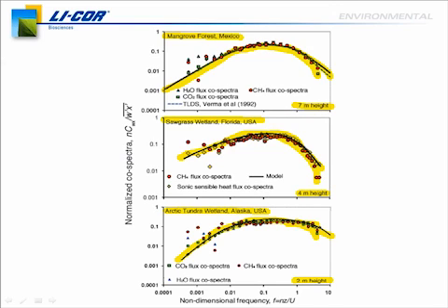We've measured this even down to 0.75 meters above the canopy, and at that point you certainly do see a more significant drop-off of the high-frequency fluctuations, which is expected, and it's very atypical for a person to put up a flux tower that close to the canopy anyway. But just so you know, there is a point where you do see more significant drop-off, and you need to watch that. But for standard flux tower heights, 2 meters or higher, we get good co-spectral response from the instrument. So hopefully that'll clear up some questions as well.